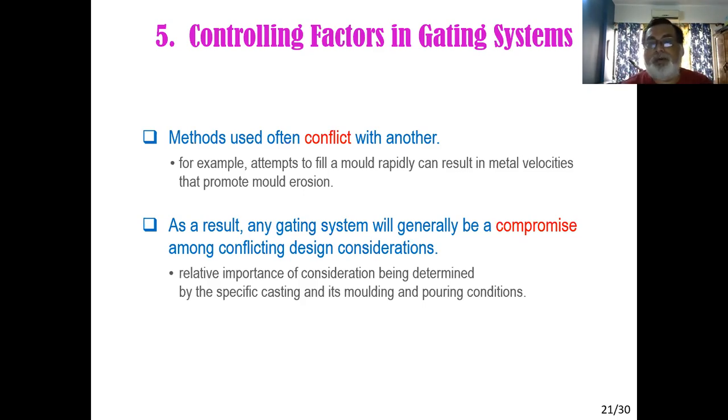We'll prefer bottom pouring system in our design. At the same time, we'll prefer unpressurized system. That means when the liquid metal flows, the area will be gradually increased in the forward direction. Probably we can use slightly pressurized system or naturally pressurized system, but we'll never use pressurized system, where the velocity of the liquid metal is continuously increased.